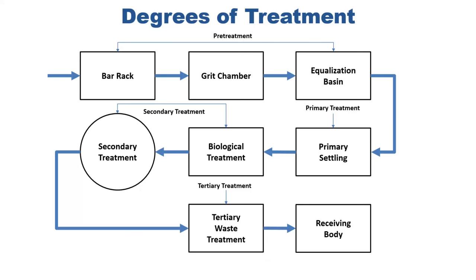Now for the secondary treatment, its major goal is to remove the soluble BOD5 that escapes the primary process and to provide added removal of suspended solids. Secondary treatment is typically achieved by using biological processes. These provide the same biological reactions that would occur in the receiving water if it had adequate capacity to assimilate the wastewater. The secondary treatment processes are designed to speed up these natural processes so that the breakdown of the degradable organic pollutants can be achieved in a relatively short time.